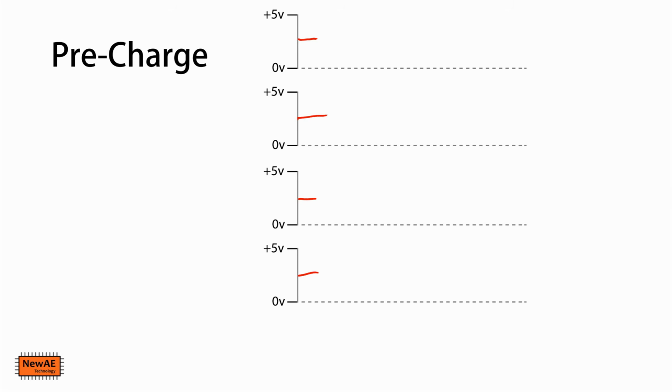Before they know what the final state is, they go into this pre-charge. And what you can see now is the worst case is half the swings required. It also means the power consumption is lower, because they're not all switching as far. So there's a lot of advantage to this from a design perspective.